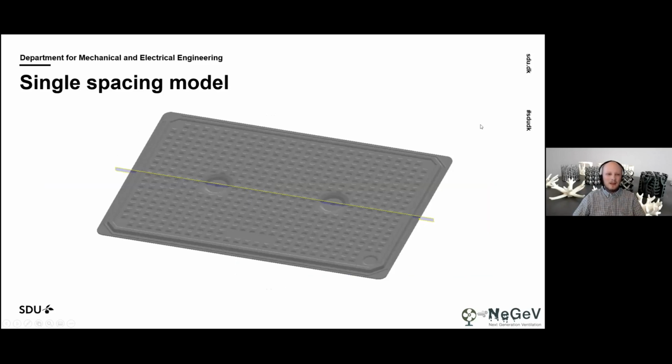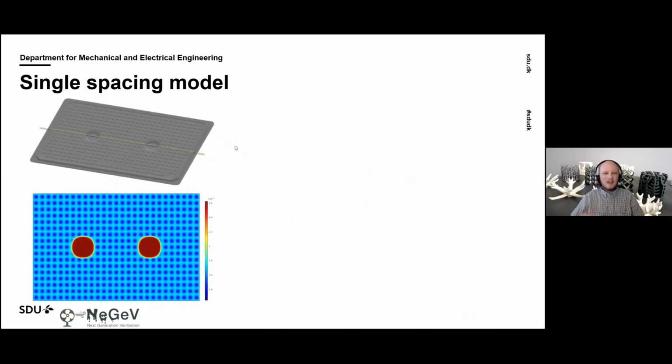simulations we have. So if we zoom in and look closer on these PCM plates, we can look at a single spacing between two of these plates. And we see that the plates have this quite complex surface topography. There are several reasons for this. Some are there because we have to be able to fill these plates using the PCM solution. These in the middle here are sort of to conjoin the two sides together. Some of these are corrugations that are there for stiffness purposes because we have quite a heavy solution.